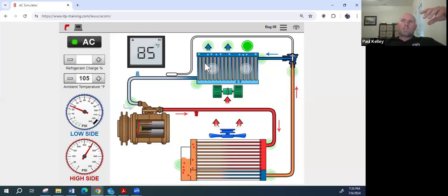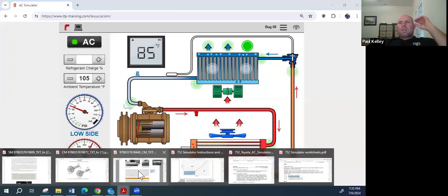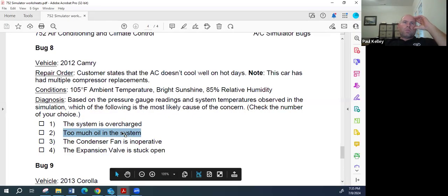We're getting the cooling because there is evaporation inside, and that's absorbing massive amounts of BTUs in latent heat form, not in sensible heat. So that oil's not evaporating. You've got refrigerant coming into this evaporator, cool, but it's way less refrigerant than it used to be. And now it's just a bunch of oil, and the oil just gets circulated. It doesn't change state. So you lose a lot of cooling. Make sense?